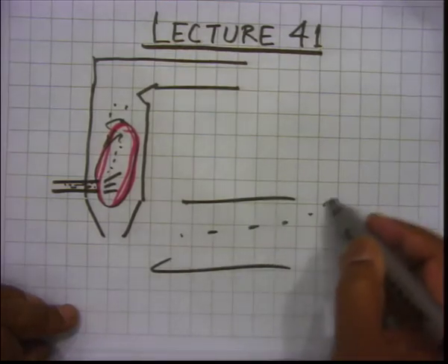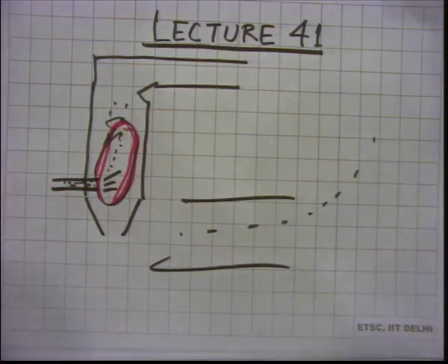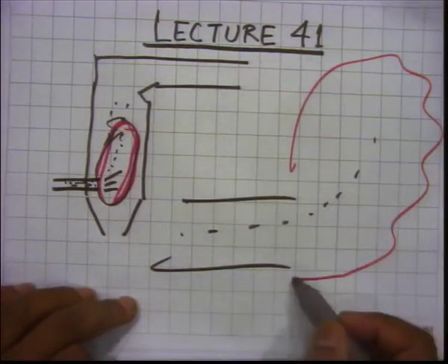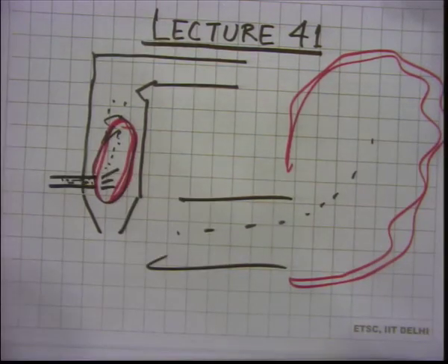These particles, okay, one particle comes. As it moves, it's not the same particle anymore because it keeps getting heated. Who is heating? This entire flame zone is heating, it's pumping in heat. So the particle gets heated. It's getting heated at a rate which is high because the flame temperature actually is quite high. Okay. So the heating rate in an actual boiler situation is much higher than what heating rate you will get in a proximate analysis that you do in a lab.